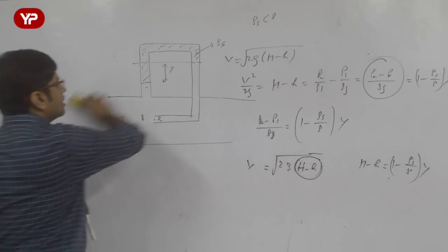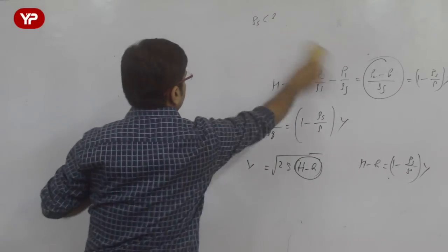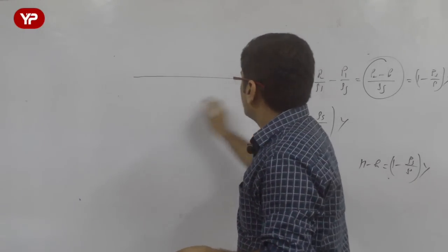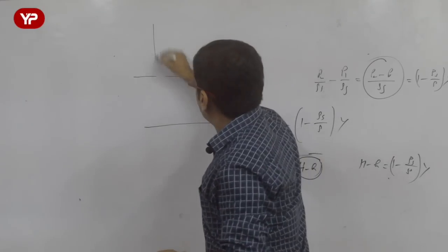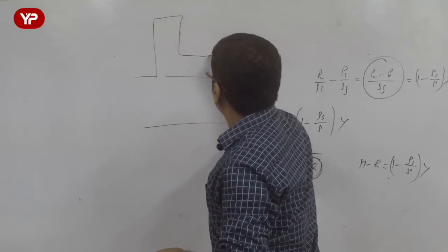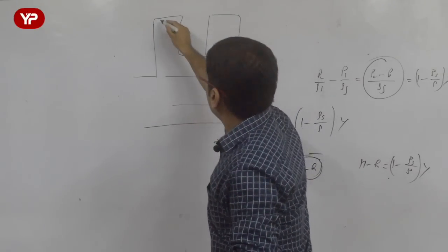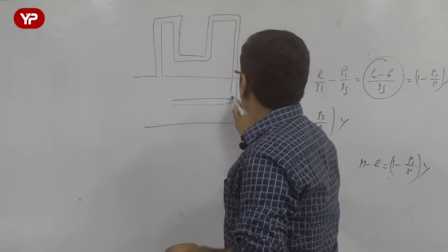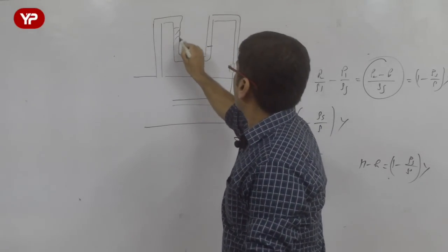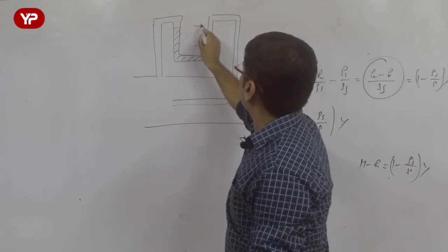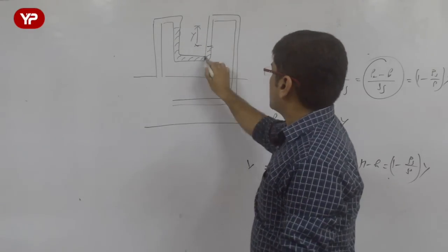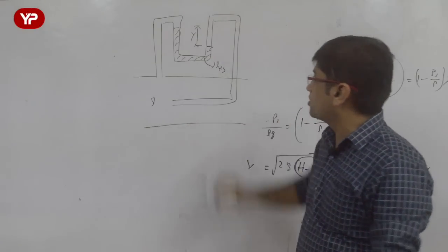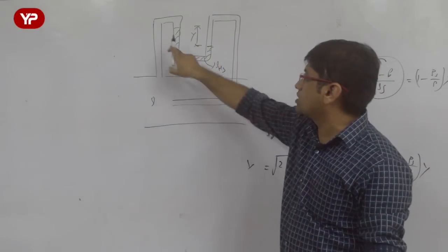Now suppose I want to use a U tube manometer, not an inverted U tube but a U tube manometer. How shall I put the pitot tube? You see what kind of arrangement I can get for that. Can you tell me what this manometer is now, U tube or inverted U tube? This is mercury. This is the fluid which is flowing, of density rho. This is the density of mercury. This is the limb difference because P2 is more than P1.